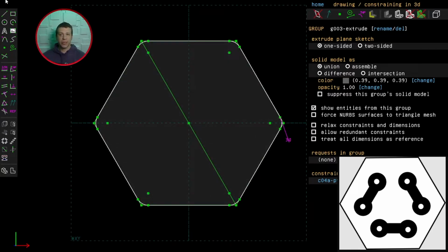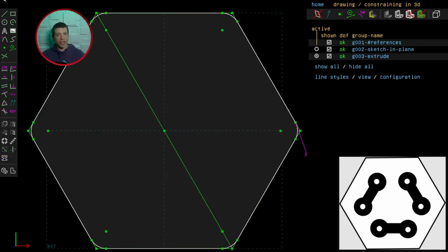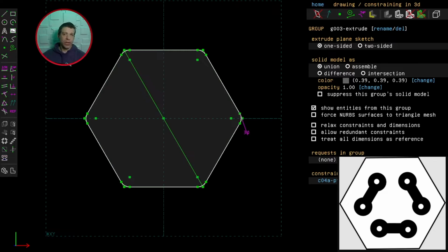Let's save it. Let's go to File, Save As, and I've called mine Base. And I'll convert this now into an STL file. We're going to File and go down to Export Triangle Mesh, and I'll call this Base Print. Okay, let's move on now and create the wires.